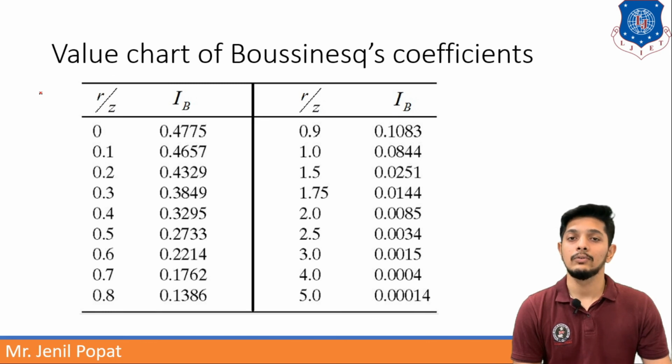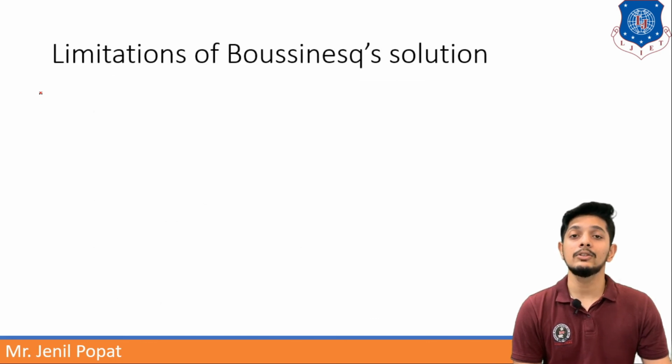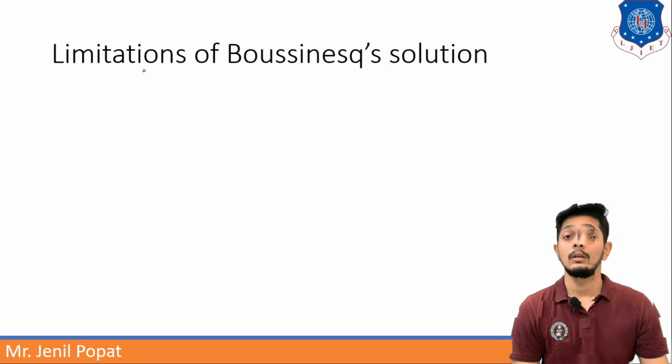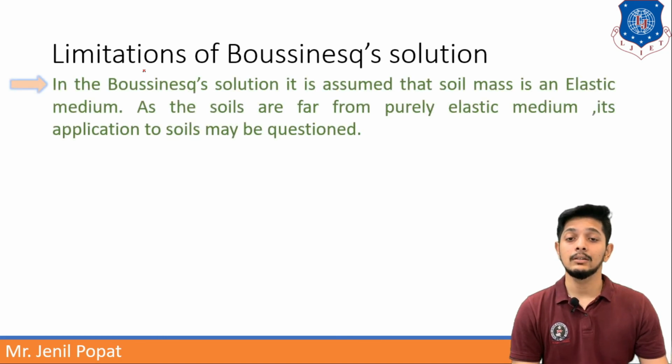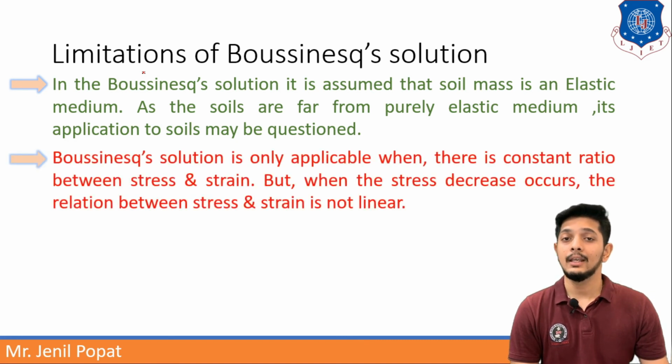Let us move further to the limitations of the Boussinesq equation. The first limitation is that in the Boussinesq solution, it is assumed that the soil mass is an elastic medium. As soils are far from being purely elastic, it is questionable to take it as an elastic medium. The second limitation is that the Boussinesq solution is only applicable when there is a constant ratio between stress and strain.